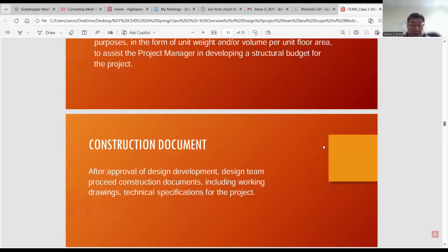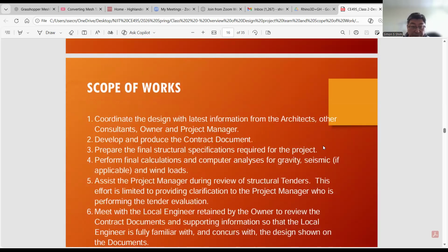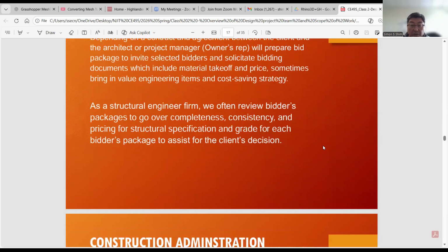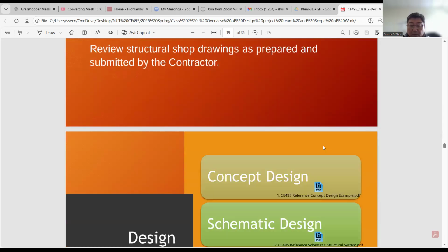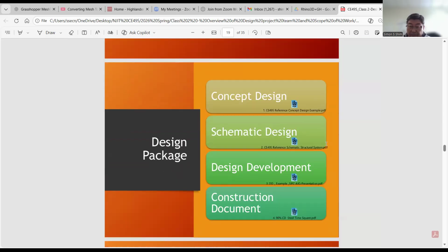All right, okay, I'm going to skip this. So based upon each phase, we are studying and developing the floor frame layout based upon the agreed column layout and beam and girder span lengths. We size those members. So we usually develop the floor framing first, with some consideration of lateral system elements in the plan and also in 3D.